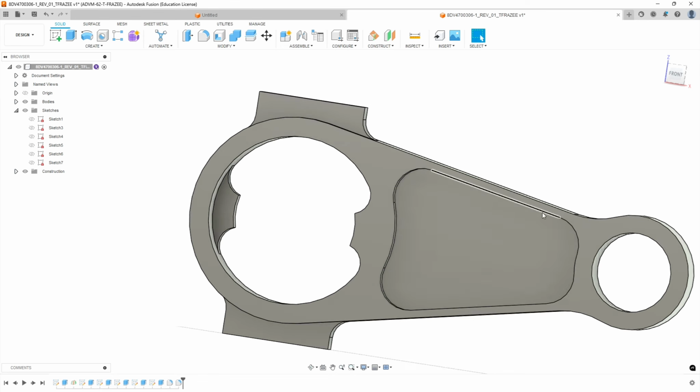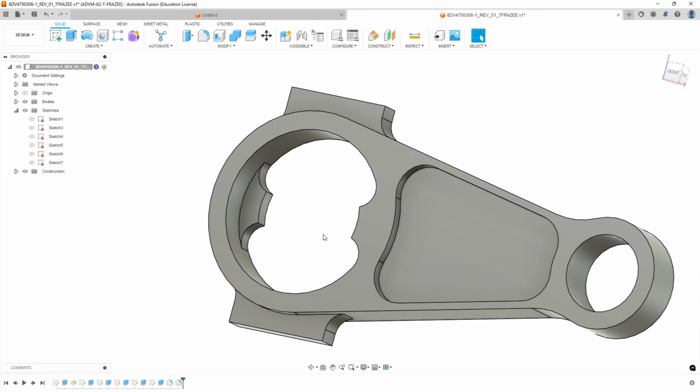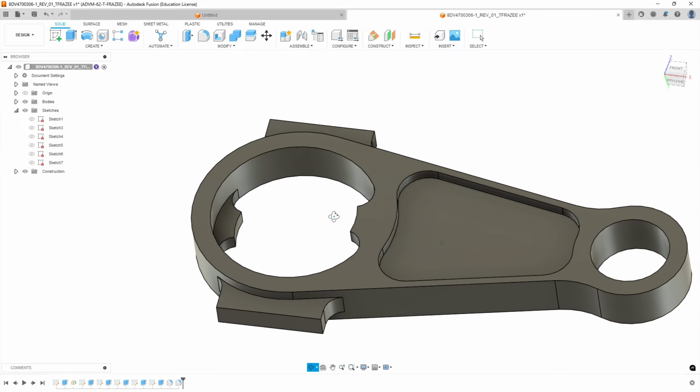So we should have all our fillets. Now you notice this one's not tangent. That's okay. It's tangent to the big arc, but it runs off. That's what we want. All our 1/8 inch fillets on the outside. All right. Now let's go to the next ones on the perimeter.